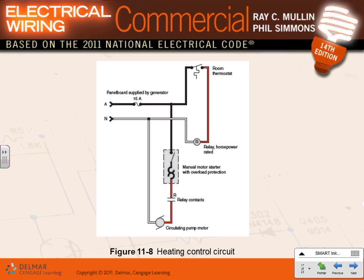Here's how it works, guys. This is really interesting. See, if one area calls for heat, it's cold and I need heat. Here's the thermostat will close. Can I get you guys to see that one? Then the thermostat will close. Then it will energize this relay. Can you guys see that relay? When this relay is energized, it closes this contact. Now this contact has a pump. Remember that recirculating pump that you have in your project? These are recirculating pumps that circulate the hot water inside the building to get your heat.